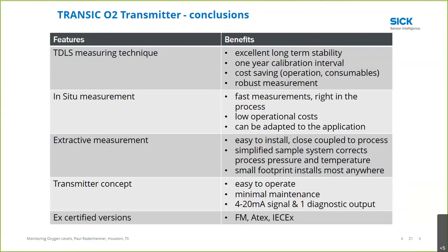Because many of the tanks are live, I have not seen stratification in the tank. In other words, they're always being swept with a purge gas, and the volume of the tank is changing on a routine basis. So it's increasing when it's being emptied and decreasing when it's being filled. What I have seen on a couple of occasions is a long dead space between the tank and the sensor.